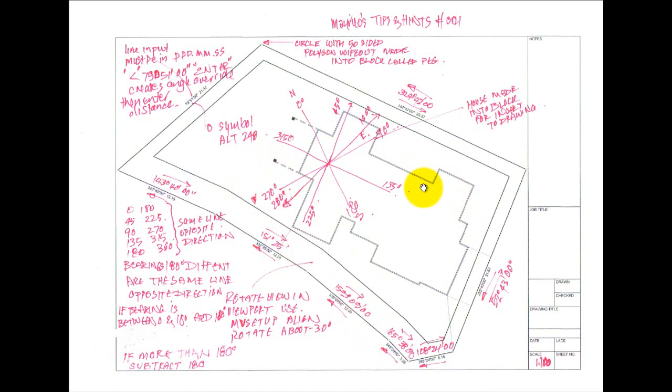Now you come to a little bit of lettering. The best thing to do, or what I did, was to set the lettering to an annotative style that's 3 meters high in paper space, and then you also need to tick the box to say that your lettering will be horizontal, aligned with the viewport. If you don't do that, everything will be aligned with the 30 degree rotation. So when you set your annotative text style, you need to make sure that it's all aligned with the viewport.